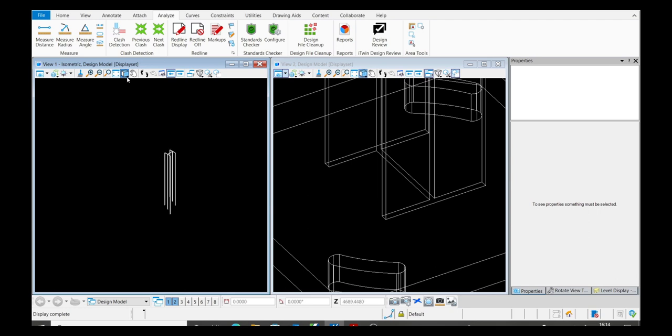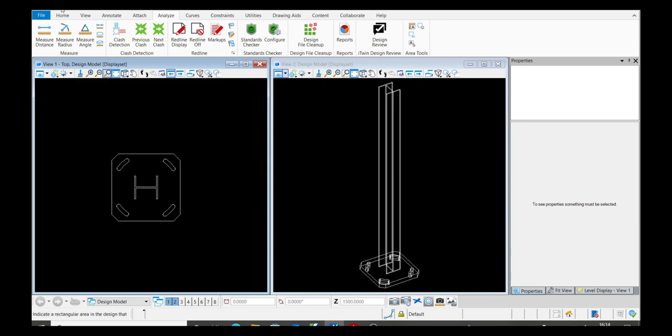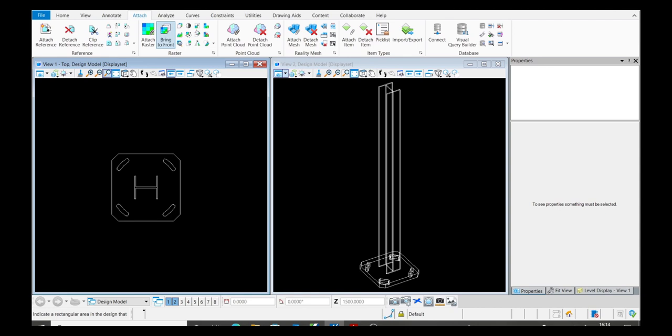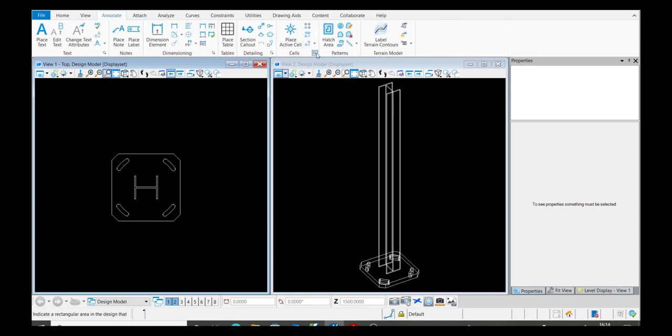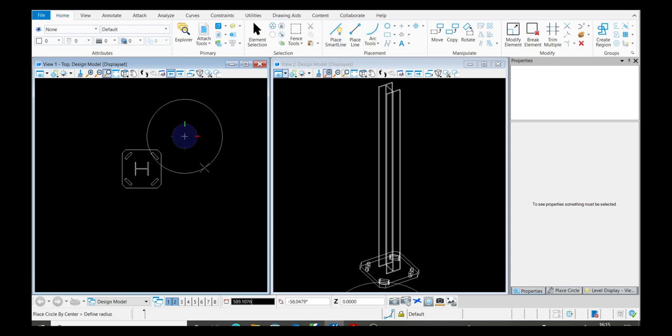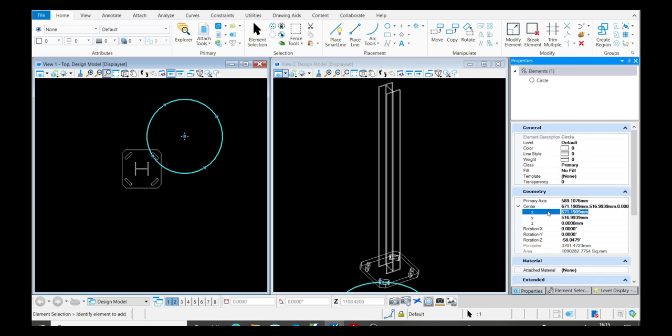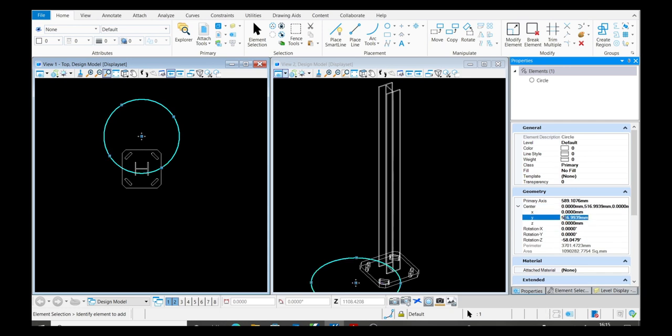So now it's about time to make it into a parametric cell. So first thing is, for me, you have to add the cell origin. It's easier if you have something that you can snap onto. So I'll create a circle here because it's just easier, especially if you drew the mast from a 0 start point. So I'll move it towards 0 and 0 here. Right, let me see. Good.